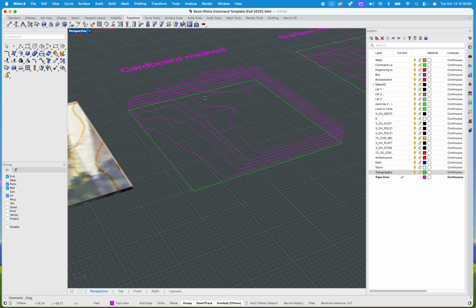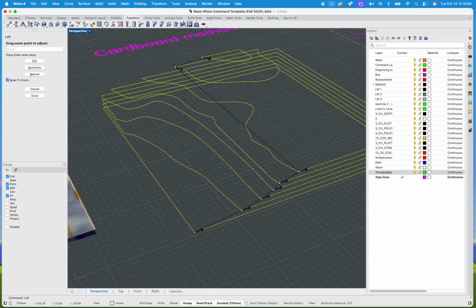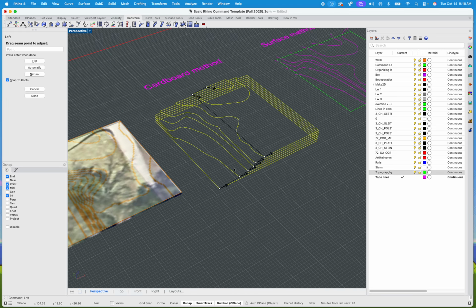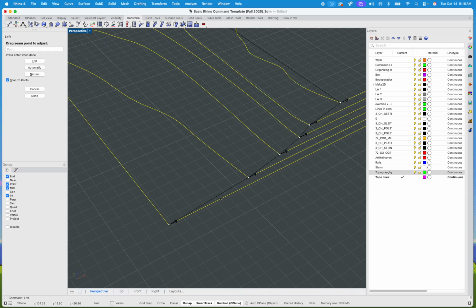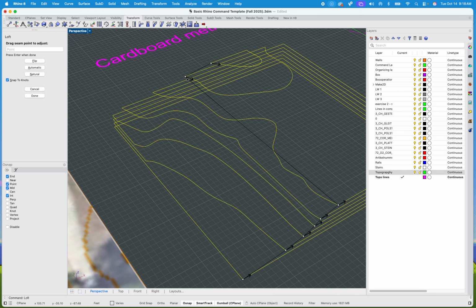I mean, don't get me wrong, that's eventually what we need. Not necessarily spatial for the laser cutter, but we do need some flat, closed curves. In my case, though, I can lock these now and turn it actually into a surface. Now, this is where, remember those little arrows that we saw? This is where things actually do start to become important. Those arrows basically represent a direction, and you definitely don't want one arrow facing one way and one arrow facing the other way. However, we also want them relatively close to each other, right?